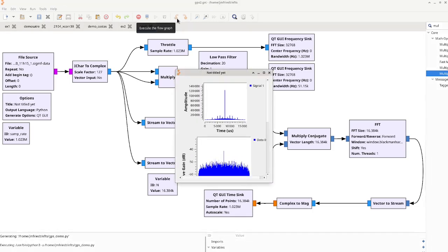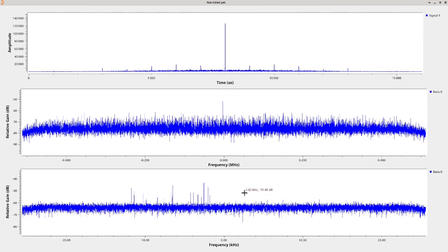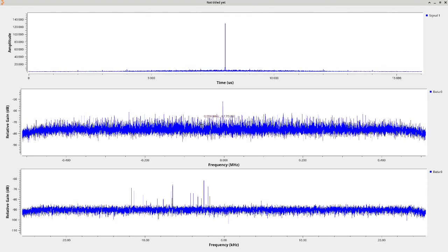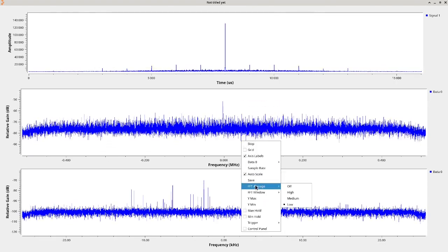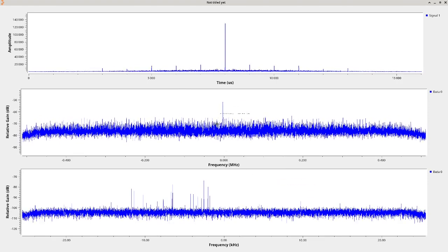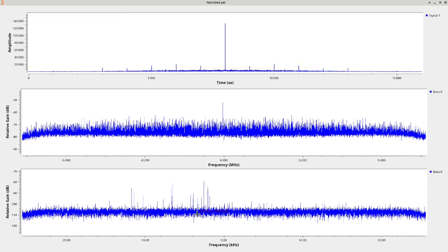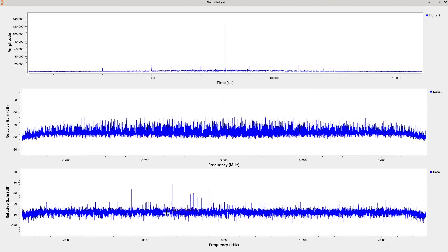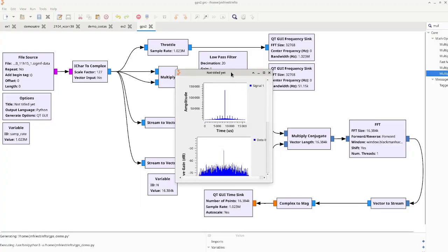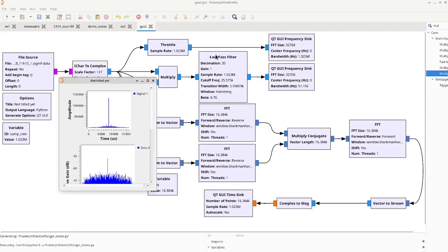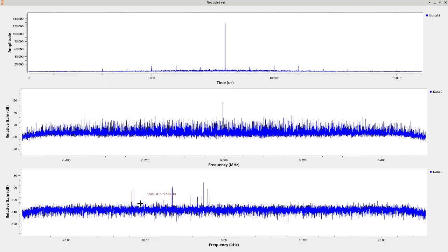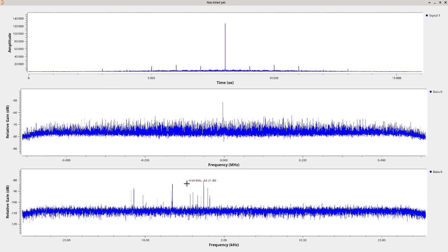And again, in this demonstration, we will see that the raw data does not exhibit any structure on the spectrum of a GPS signal. Squaring the signal does allow for identifying the various satellites, and this time we have included a low-pass filter to zoom in on the central aspect of the spectrum by getting rid of the outer parts of the spectrum which do not include any relevant information.